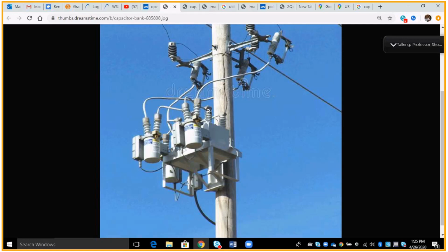I take it up to the bank cell and I test 1. It's hard to see in this picture. There's my next one. I test 2. I test 3. I'm on my noisy tester on the bank itself. All of them are de-energized. Now I know I will not be breaking load. The vacuum bottle did that for me. Now I can open my fuse cutouts.